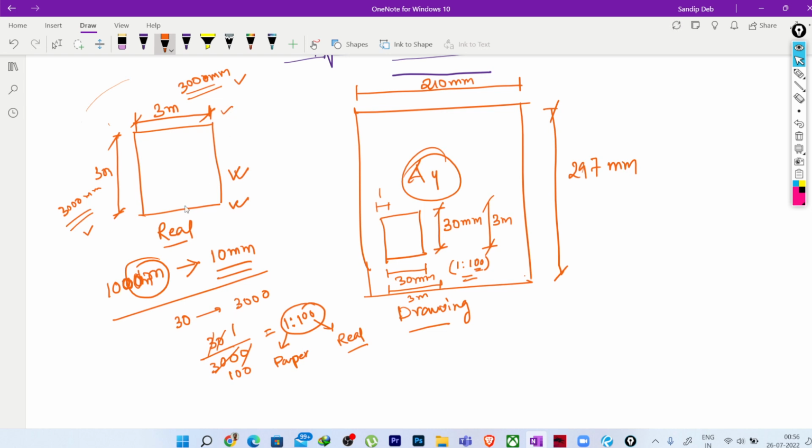But now, when we are plotting the drawings on paper, we are scaling it down, but we never write the dimensions like this. We always write the actual dimension, so that the engineer working on the execution does not have to use those scalings. These scales are only used to make one understand how we have made the reduction, but the dimensions we use are the actual dimension itself.